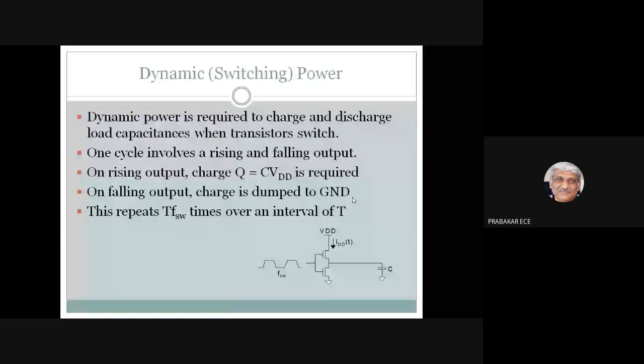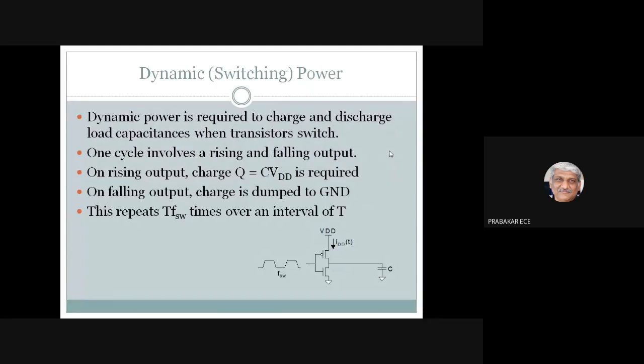This is what I said. I think you can see the diagram here. VDD is connected here. There are some NMOS and PMOS transistors. At some point, when the transition is 0 to 1 or 1 to 0, at some midpoint, what happens? Both the NMOS and PMOS will be in the active state. And in that case, there will be a short circuit between VDD and ground. So whenever there is a transition, the power consumption will be high.